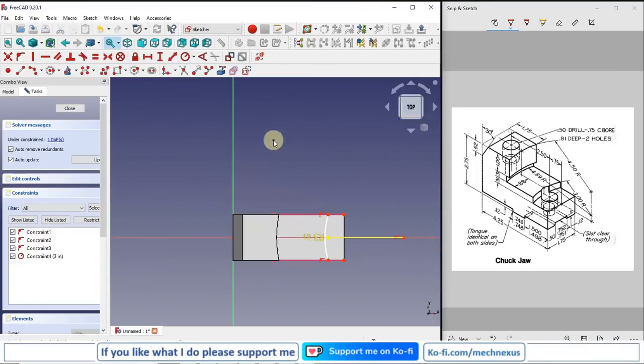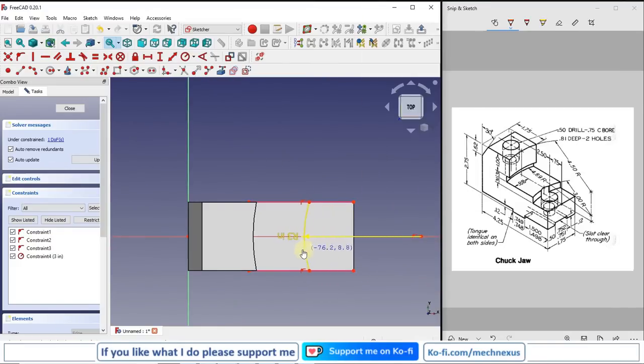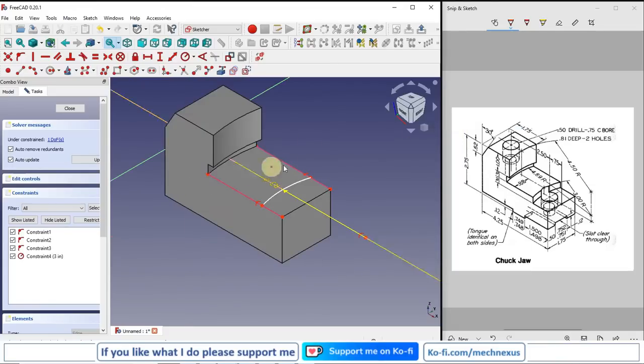Now we will see what is unconstrained. So the position here is unconstrained, so we will look for the position. Its position is concentric with our first cut which we have made, so we will project our first cut, so we will get the center points.